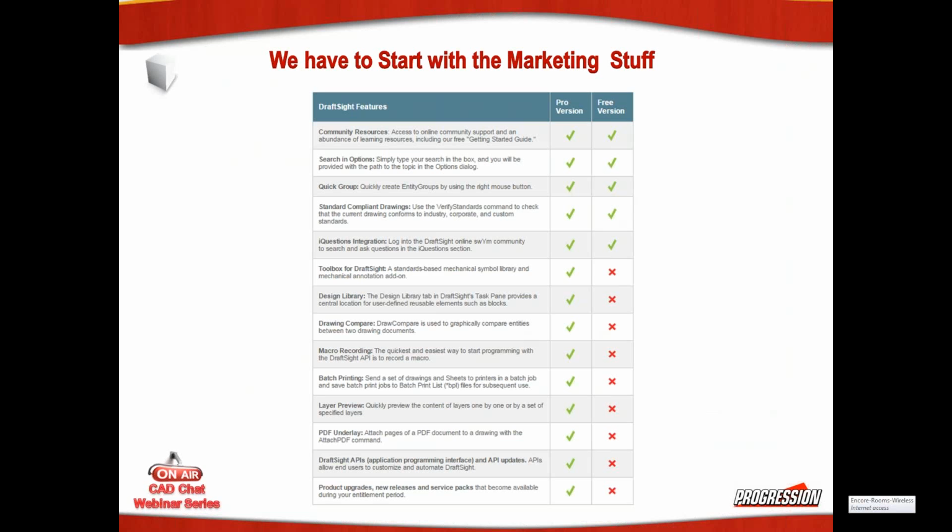And really what you use it for, if you're a company who creates flat patterns and has to dump those flat patterns out to a DXF, DWG file for the shop that actually does the cutting, the free version's great. It lets you dump your SolidWorks drawing out, open it up, check the DXF file, make sure everything's readable, looks good, and then send it on to your